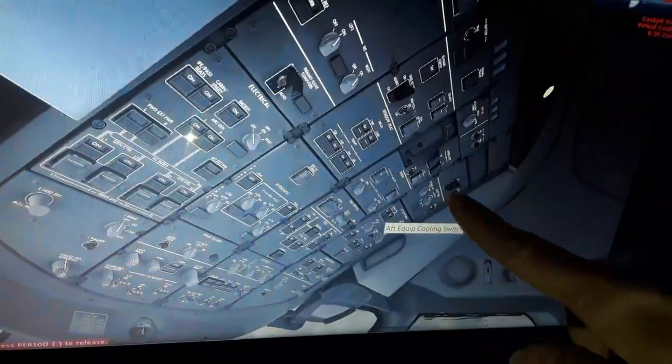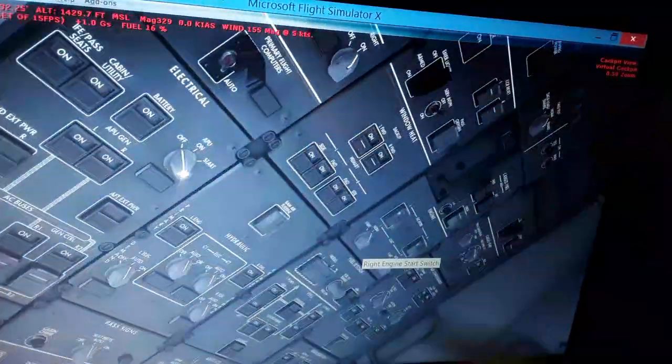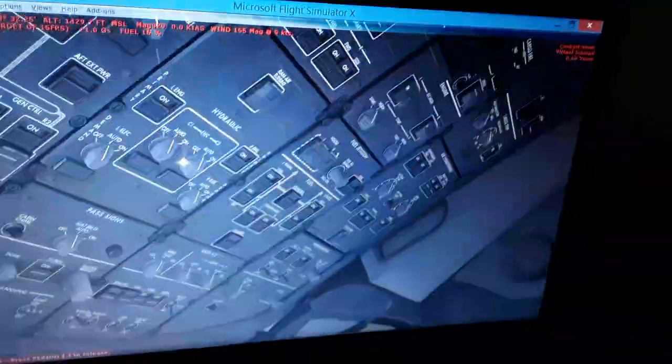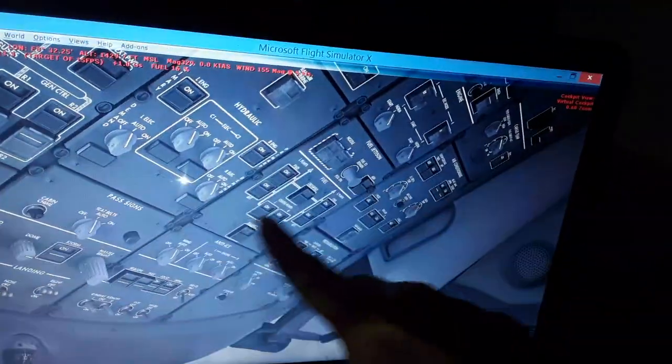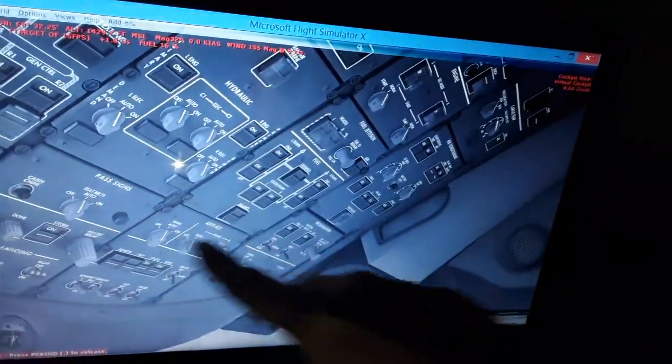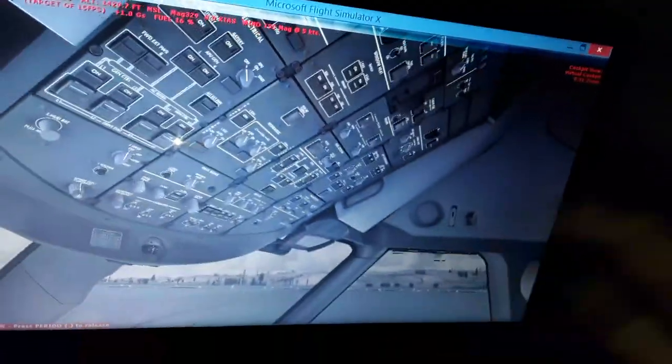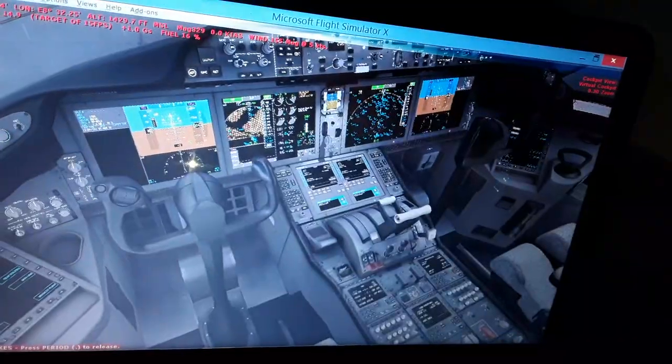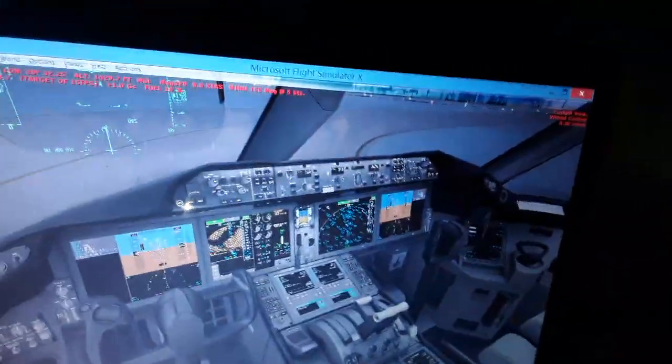So we have bleed air for cabin pressurization from the engines or the APU. We're going to need the APU also to start the engines. Also hydraulic fluid tank pressurization, engine anti-ice, and oxygen inside the aircraft. When flying we need pressurization from the engines.